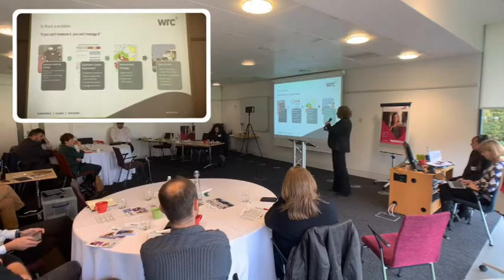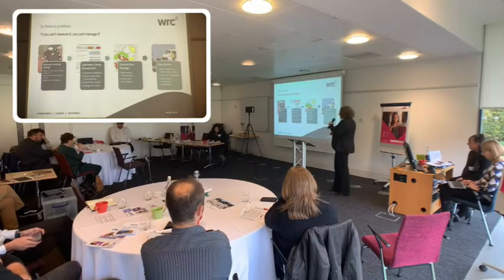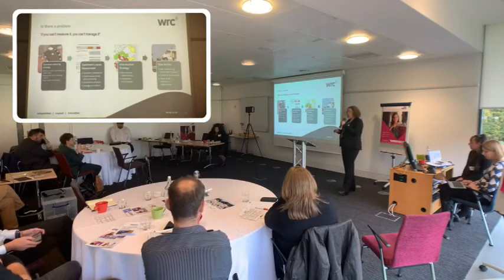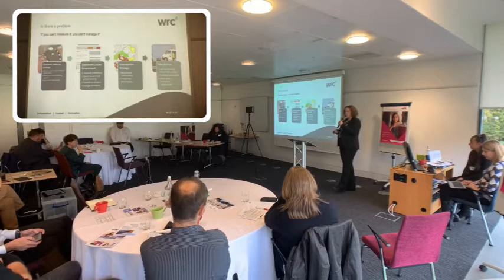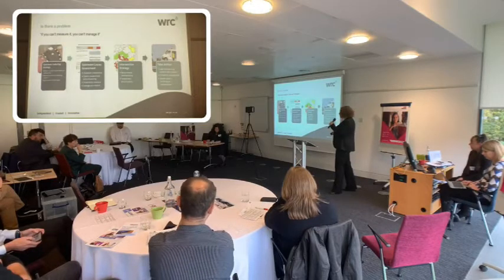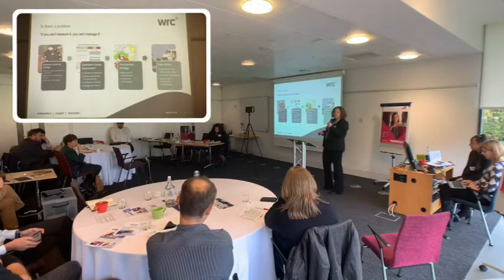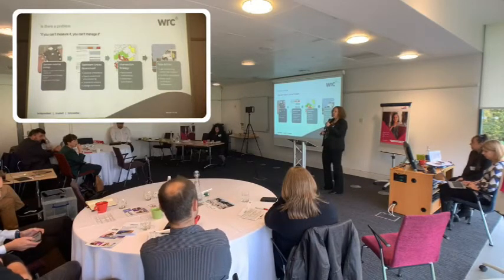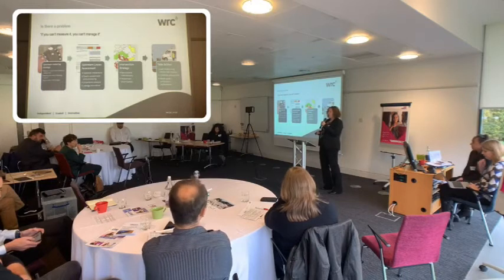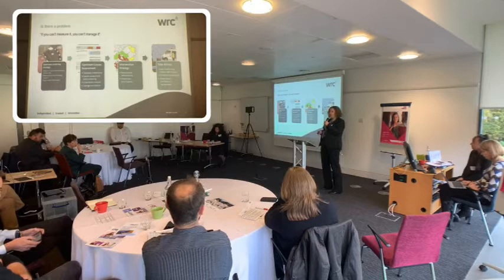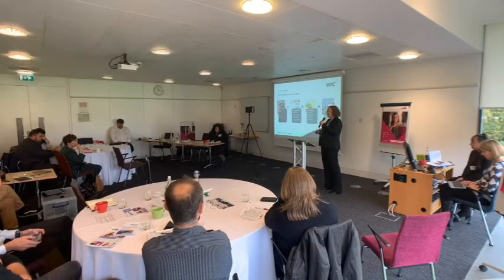So to measure upstream leakage, you're going to need meters, big meters on these big pipes. You need to have a good strategy to make sure that those meters are sized correctly and put in the best locations to be able to break the upstream network down. And also to make use of existing meters and understand those meters. Do you actually know which asset is out there? Do you know what type of meter it is, when it was installed? Have you matched the serial number to the age that you think it is and actually checked that that makes sense?